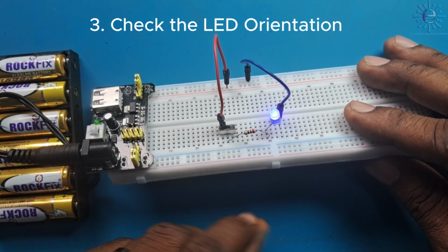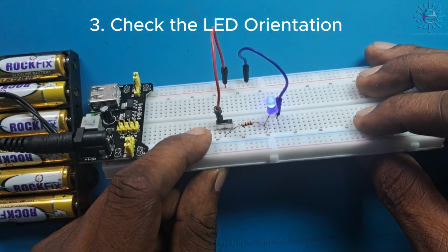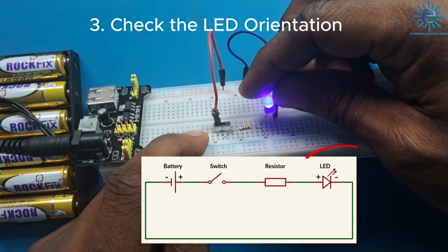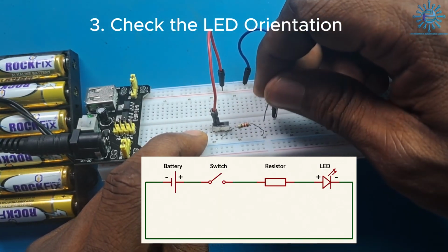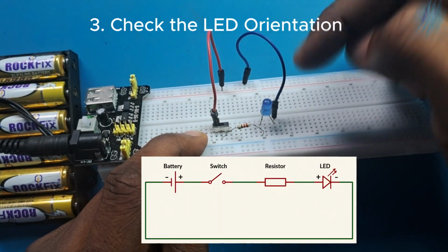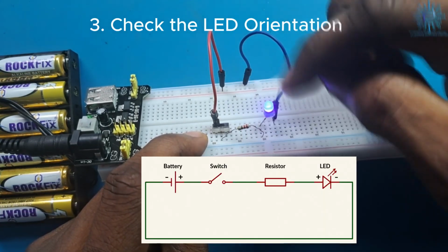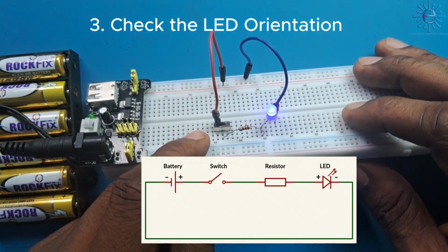Check the LED orientation. The LED is polarized, which means it has a positive leg and a negative leg. Make sure the LED is connected in the correct direction, as shown in the circuit diagram. Imagine we reverse the connection of this LED. Instead of having it this way, I reverse it this way. You can see that the LED did not come on because the LED has been connected in the wrong direction. So check whether you make that mistake and then correct it by connecting the LED in the right direction. When you do that, the LED will start working as expected.